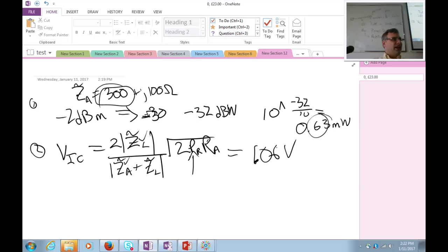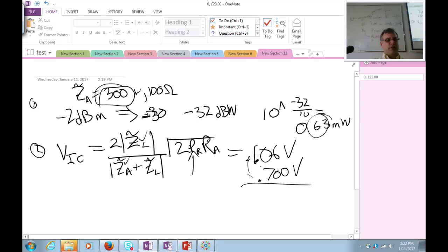Remember what I mentioned in the previous class period, that a diode has to turn on. What is the turn on voltage of a silicon diode? I think you said 0.7. Yeah, that's the classic doped silicon diode. It turns out you can change the doping and change the turn on voltage, but that's a nice standard textbook value that everybody learns in their freshman or sophomore circuits class, right?